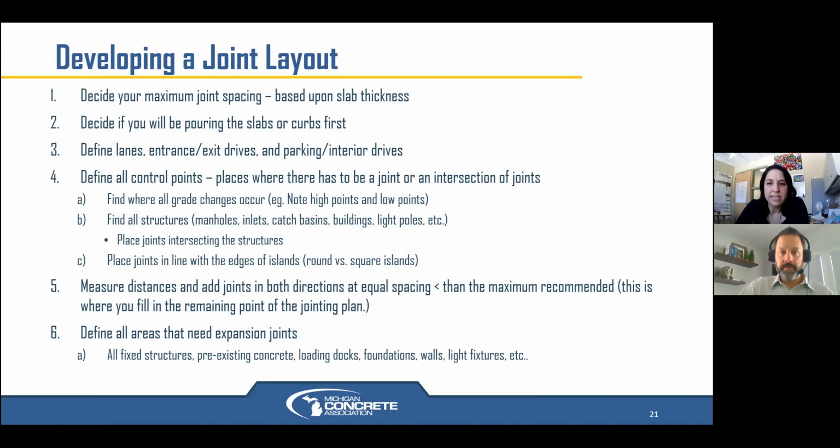And then we have, what's the best jointing practice to isolate round structures, specifically when replacing utility poles? There's a couple. Steve? Yeah, there's a flexible foam expansion material that I'd recommend that you can find in varying widths. I would not use the MDOT standard asphalt impregnated fiberboard, which is designed to remain fairly rigid and cannot go around round structures.